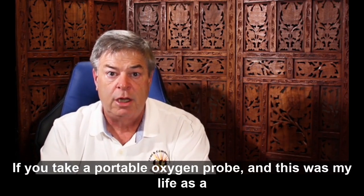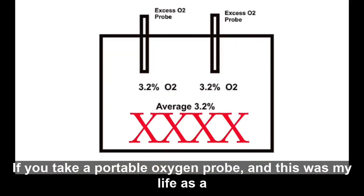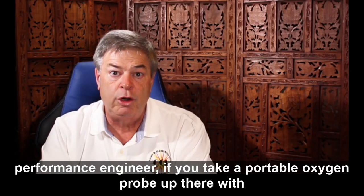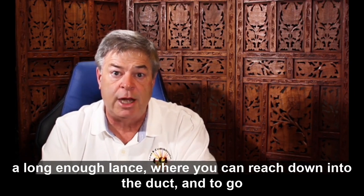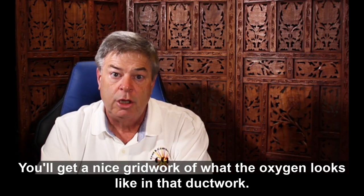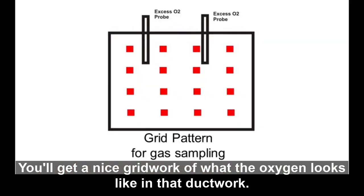In many cases, the O2 probes are up near the ceiling, put in this way, and they don't cover the whole duct. If you take a portable oxygen probe, and this was my life as a performance engineer, up there with a long enough lance where you can reach down into the duct and go through several different ports across the duct, you'll get a nice grid work of what the oxygen looks like in that ductwork.